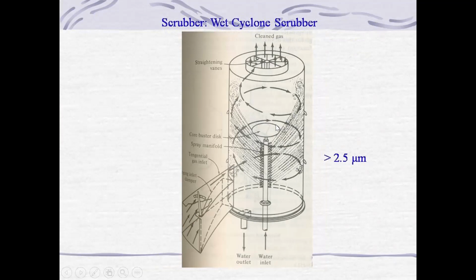But in the cyclone separator, we provided the inlet at the top, and that's why the gas was moving in a downward direction first and then upward. But here in this structure, we have provided the inlet at the bottom, and that's why the gas is moving in an upward direction directly. So there will not be the double vortex.